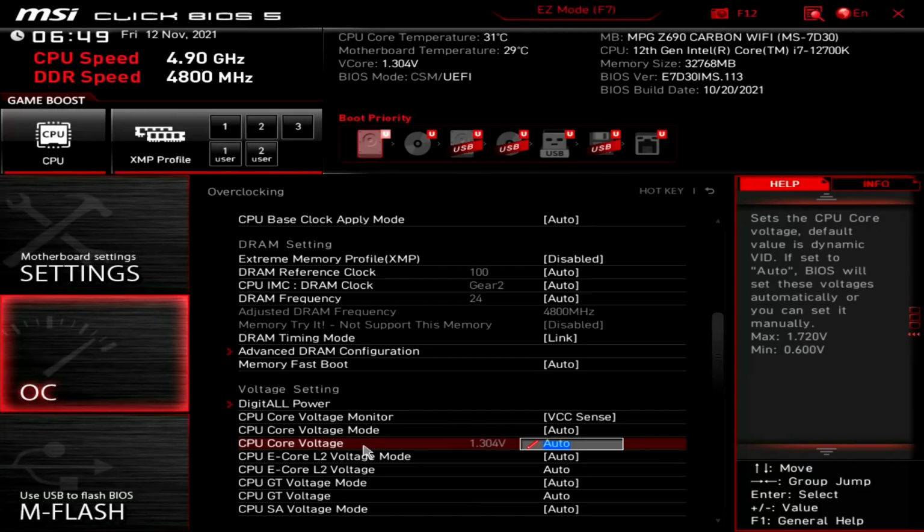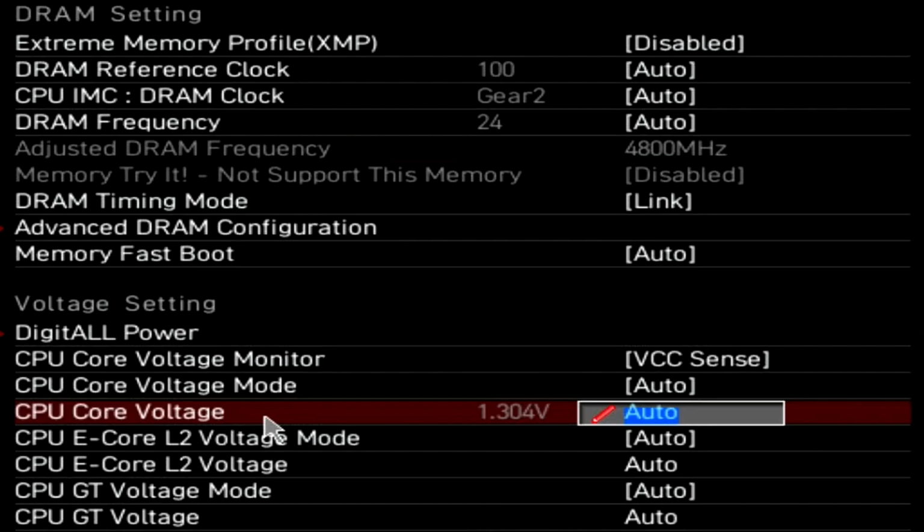Returning to the BIOS, we can now understand what the voltage indicator next to the CPU core voltage really means. This is the current VCC IA voltage, which is determined as the highest voltage as requested by the active CPU P-cores, E-core cluster, and ring. The keyword in that last sentence is active.